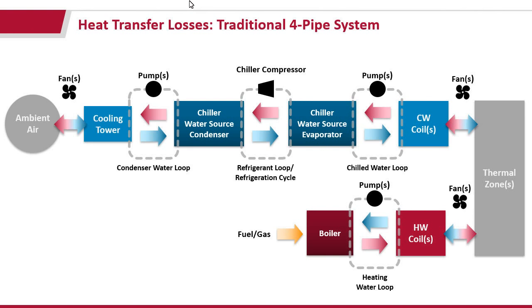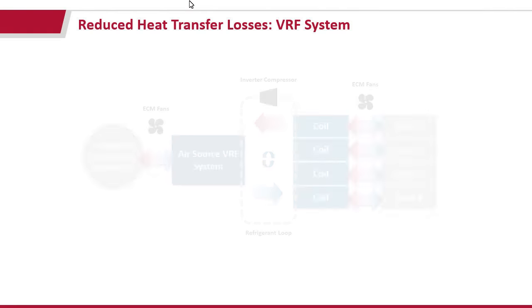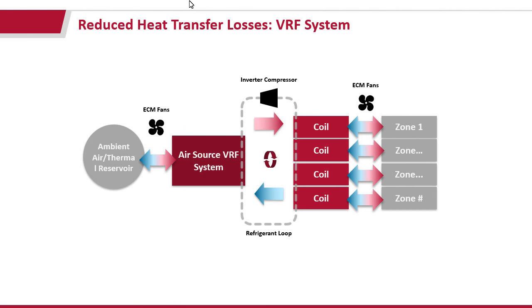And then if you want heat, you obviously have to have a boiler too and input gas. So comparing that to, like I said, the heat pump version where you have one cycle and then you can run it in reverse, the same system, and you get exactly the same pieces of equipment, but giving you a whole other operating mode. So again, space savings and then energy savings because you're not transferring your energy so many times to make it go to the same location, which is inside your building or your conditioned space.